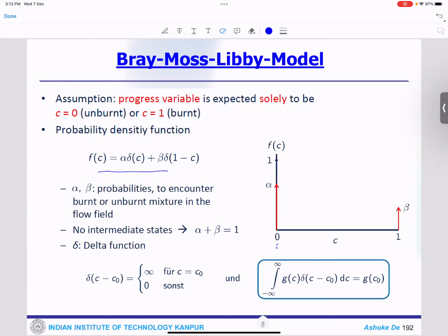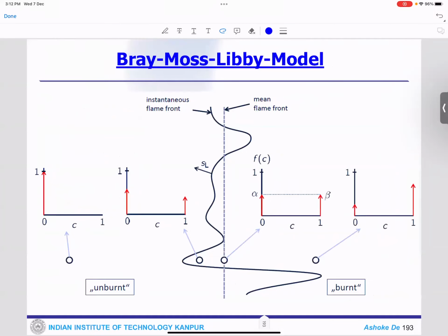So once you have the pre-computed table of the flamelet library and things like that, that pre-computed table you actually use to estimate your temperatures and other things. So this is how you do that in between. On both the burned and unburned sides, you have the flame front which will pass through, and you try to capture the information.